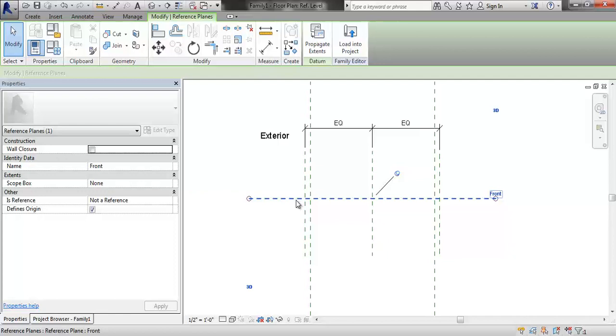In case B, I need a slab edge cover, right? So if my slab is coming in this way, I need to cover that slab in some fashion, so that way I handle any thermal break. Who doesn't know what thermal break is? You guys are learning. And that's just for airflow. So I need to build that into my family.